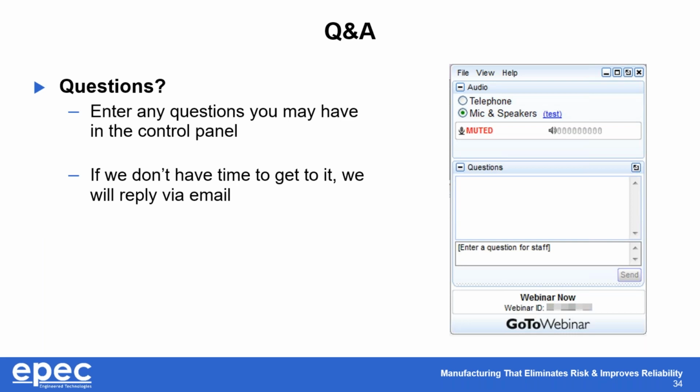So under those circumstances, it might force the flex to be hand assembled, which, in a small quantity run, can be considered. In larger volumes, definitely not the preferred solution. In general, we find that adding a ferrite to a flex circuit works best if the flex is a ZIF connector design, where there's no additional connector required. So you'll have at least ZIF contact fingers on one end of the flex circuit, which will allow you to thread it through the ferrite without compromising the assembly process.